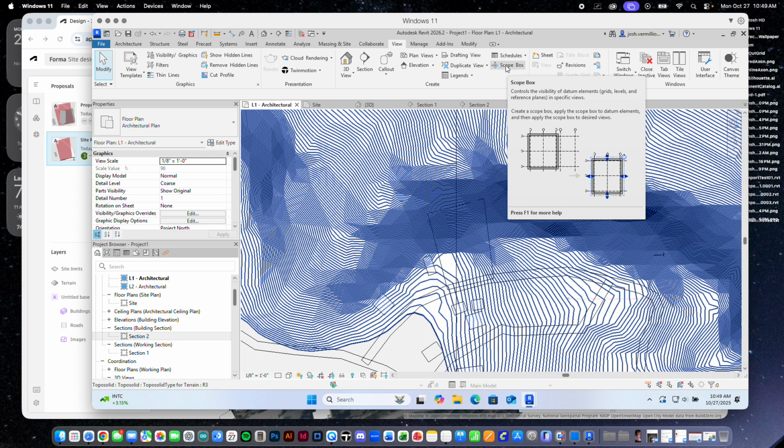and make sure that we're on the same page when it comes to being able to zoom out and see our entire site. Go into section, move our levels up and down. Go into plan, cut a section and manipulate our section cuts. And then, between plan, section, and axon, be able to add our own scope box and start to format this for our own needs, okay?